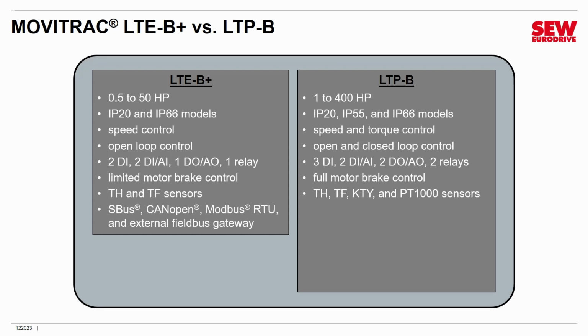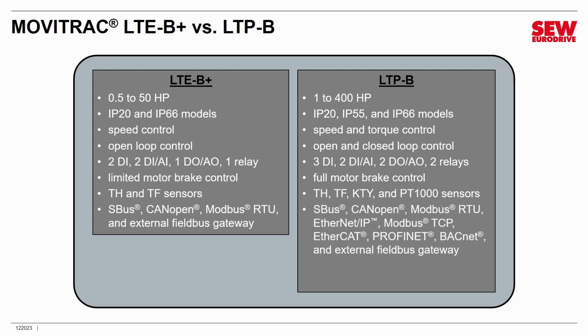It supports SBus, CANopen, and Modbus RTU, and it supports additional fieldbus standards, including Ethernet-based ones, through an external fieldbus gateway. The LTP, on the other hand, supports SBus, CANopen, Modbus RTU, EtherNet/IP, Modbus TCP, EtherCAT, PROFINET, BACnet, and some additional standards through an external fieldbus gateway. So definitely more connectivity available.